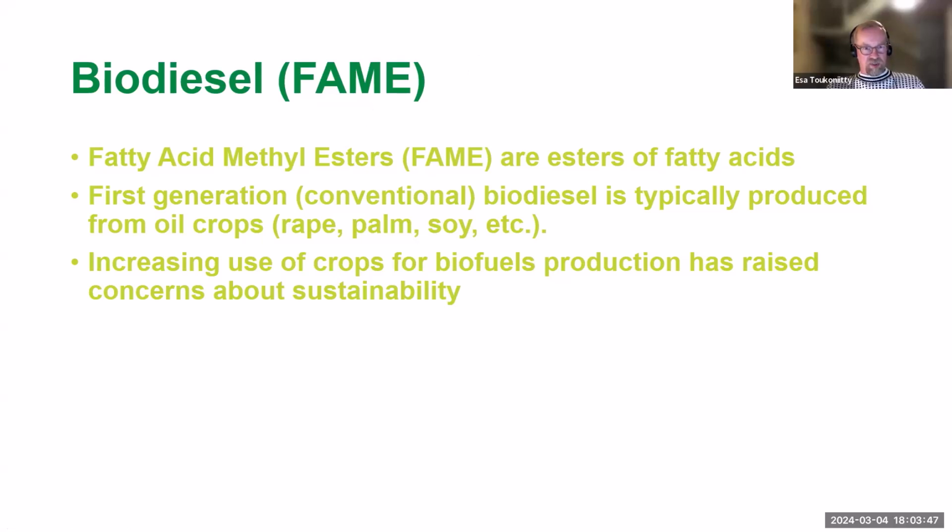Typically, like I mentioned in the introduction, it's used just as an additive. The modern diesel car doesn't run with pure 100% FAME. It might end up breaking the engine. So this is just used as the biocomponent or bioadditive.